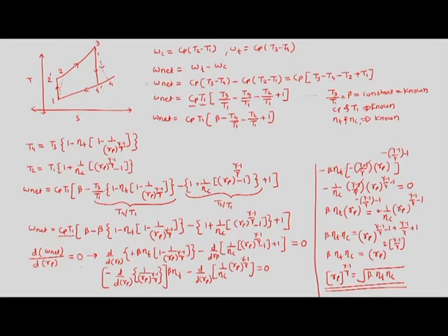So, here we practically end the part where we were talking about non-ideal components. We have to keep in mind that the things won't change except that we will have turbine and compressor efficiencies. Those efficiencies will be used to find the temperature at the end of the turbine or at the end of the compressor. The rest of the things would remain the same.